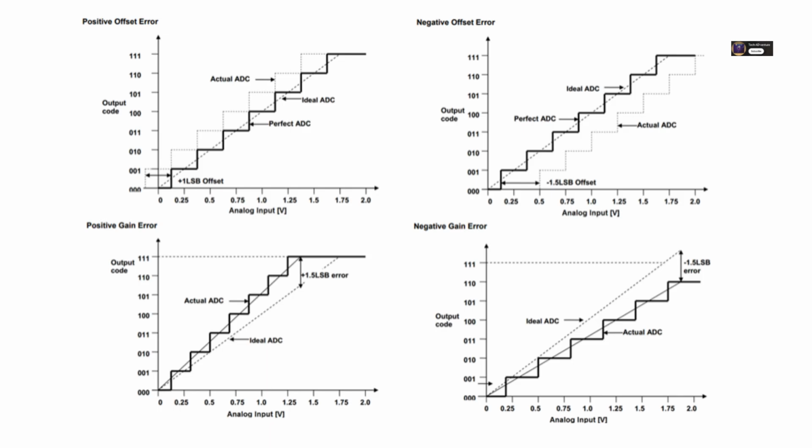Most modern microcontrollers provide ways to perform calibration. You might do a 1-point calibration, measuring a known 0 point, or a 2-point calibration, measuring 0 and a known full-scale point, to digitally calculate and remove these systematic offset and gain errors. And for random noise, like thermal noise, averaging multiple readings or applying digital filters can significantly improve the stability and consistency of your measurements. You also mentioned different operating modes.